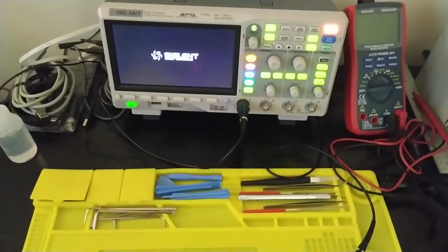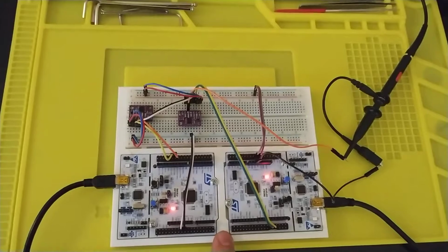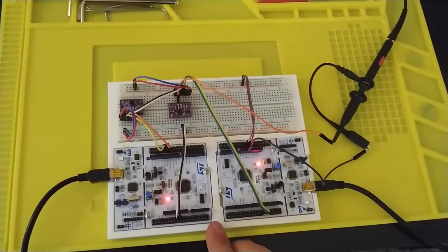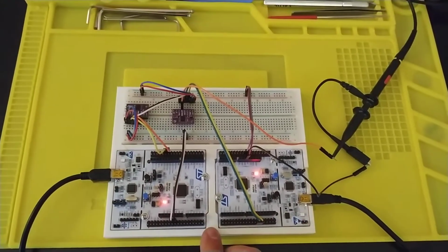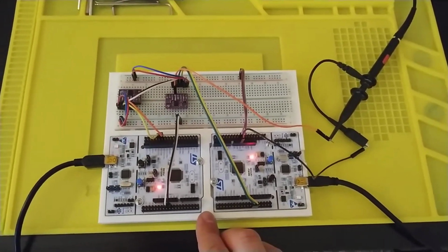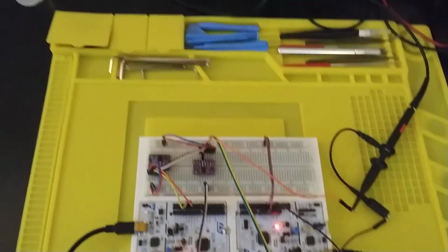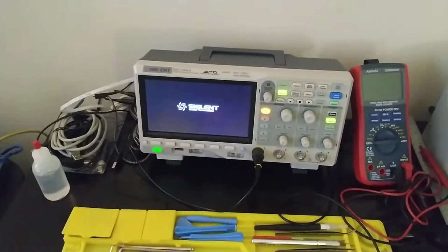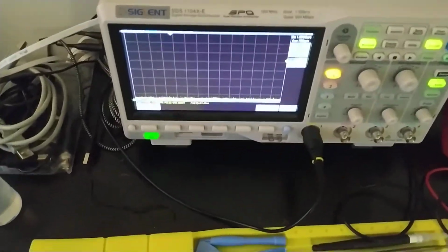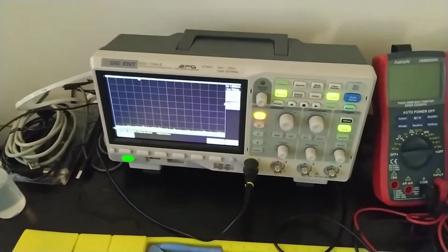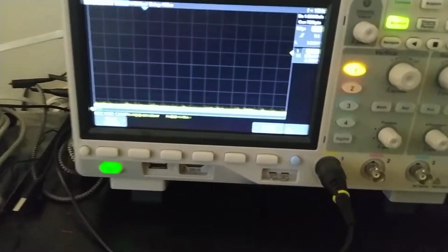Now the baud rate, how many bits per second: because we're using CAN here, it's going to be 125 kilobits per second. So the bit period, 1 over f, is about 8 microseconds. So we're going to take a look. What are the settings? What do we expect this to be at? Here, you boot up the scope. Just to let you know some of my settings.